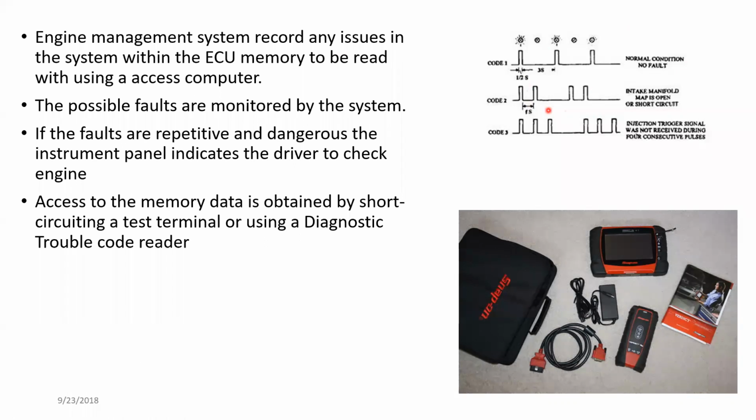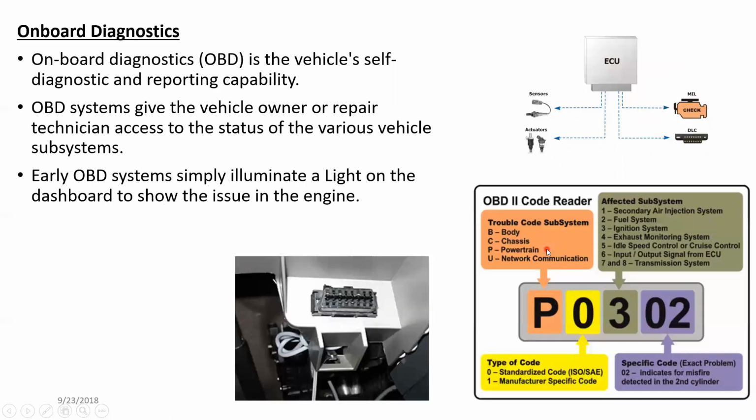That is also possible. The system in the first image is almost not in use at the moment, because it's quite difficult and there's a possibility of misdiagnosing. The light switching on and off has gaps, and the timing has to be measured properly, otherwise you will make a big mistake. So this is almost not used, but the DTC code reading system is very much available.